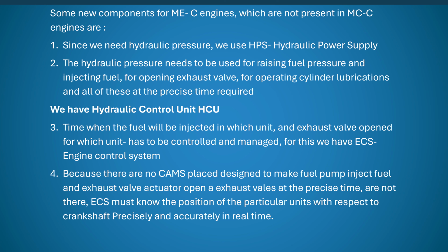Of course, it will be managed by the engine control system, but the actual task will be carried out by the HCU, because until the hydraulic pressure enters, further action will not take place. So it is the engine control system which directs the HCU to allow the hydraulic oil to go and carry out the function. Because there are no cam plates designed to make the fuel pump inject fuel and the exhaust valve actuator open the exhaust valve at the precise time.